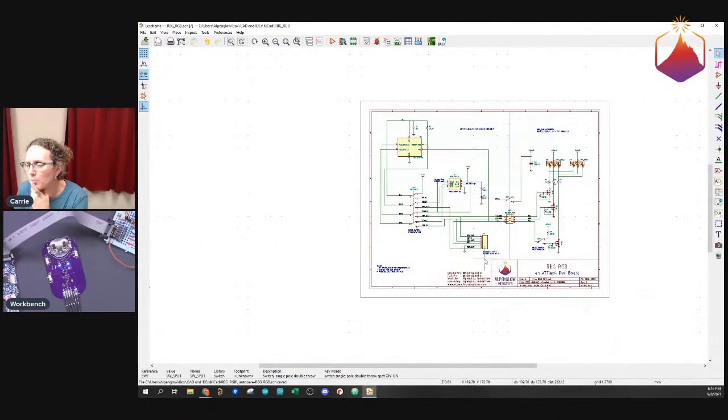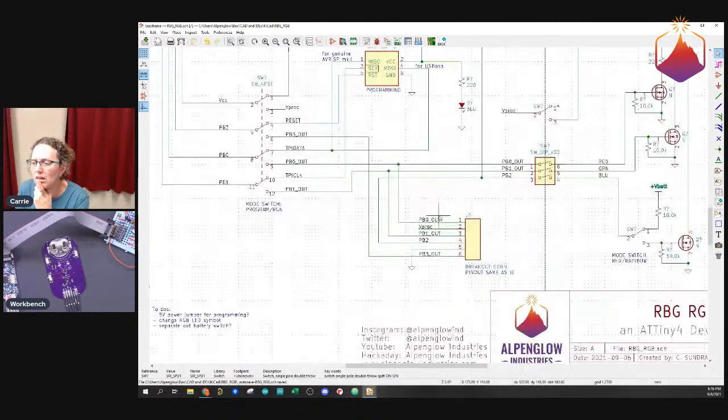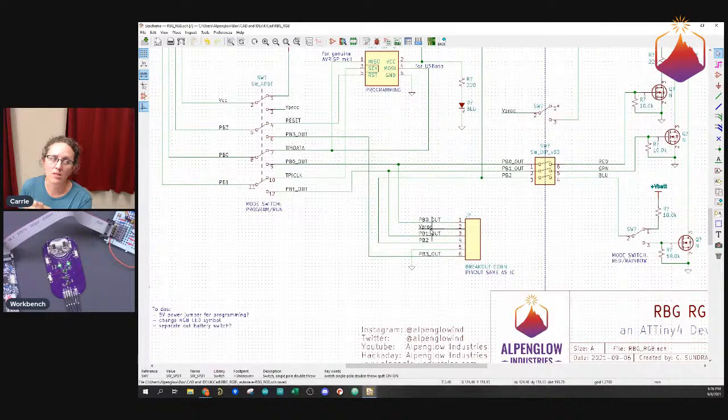Yeah, so it'll work, but you will have to be careful to not be powering this board simultaneously, essentially. So it will take a little bit of user caution in that case, because if you're giving this board power on the V processor pin, if you're giving it 5 volts to program, and this guy is connected to your battery, then you're gonna short the battery to 5 volts, and that'll be bad. Okay.